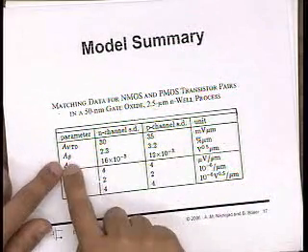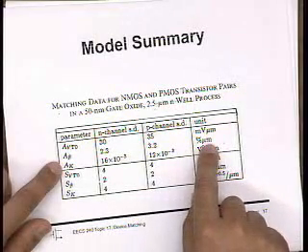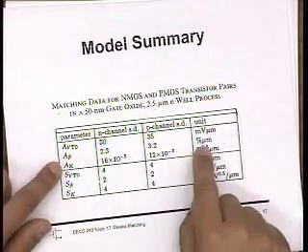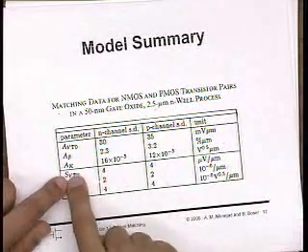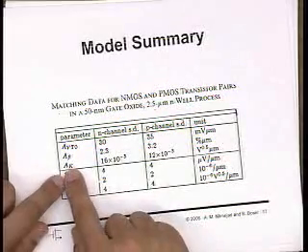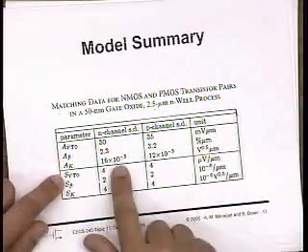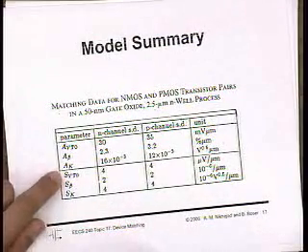This is our beta mismatch. This is a percentage times micron, again, divided by square root of area. And then the K factor here is also the gamma factor. It's the body effect coefficient mismatch. That's very small. Usually people don't even look at this.